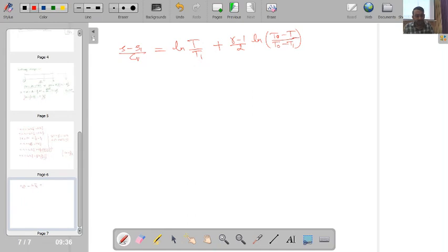Interestingly, from this equation we get an idea of what will happen if friction is involved. We know from the generic equation of entropy that ds is equal to delta q by T plus delta S generation. Is this clear? Now when we consider flow with friction, our delta Q is 0 because we have an adiabatic situation: no heat addition, no heat removal.